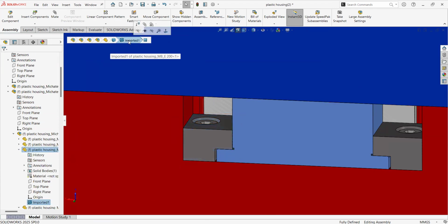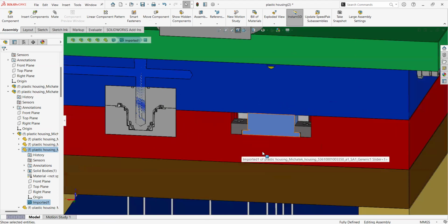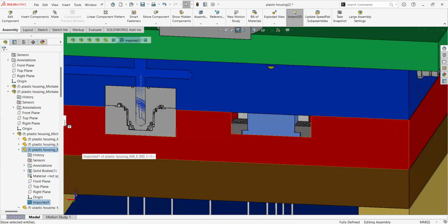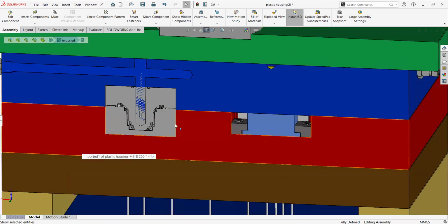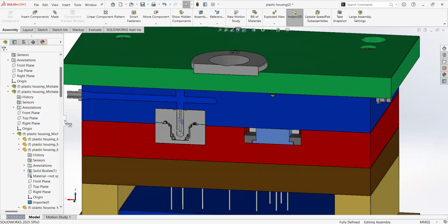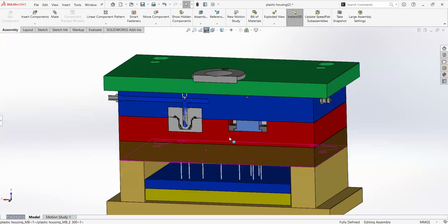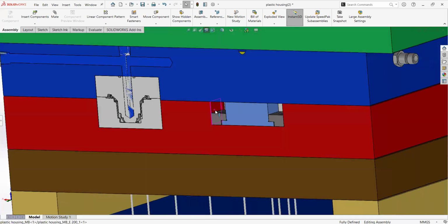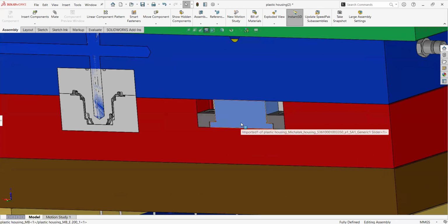In the case of features, in case of native files, I have the chance to see options that I don't have in here, but options to modify the feature, edit the sketch of the feature, and all that. And all this without having to go to the left to the Model Tree. So I could perfectly work without the Model Tree, hiding it at this dot, and doing my edits of the model without having to go to the Model Tree.